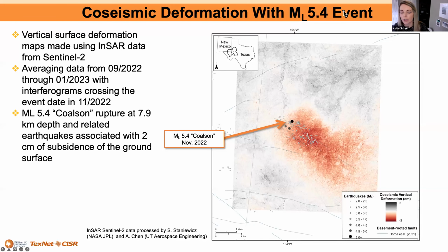Regarding the InSAR, did you also look at the horizontal displacement component? Did that show any indication of fault-related deformation? Great question, Kevin. I did. We do have an east-west deformation map, and I just looked at it this morning. We don't see a lot of anything really that I can pull out as signal. There's a lot of noise in one direction or the other. The magnitude is similar, 2 centimeters east or west. I don't see anything really that looks like fault-related deformation in the horizontal displacement.